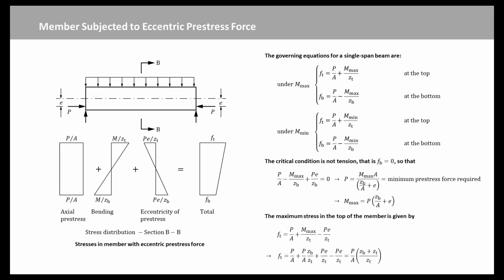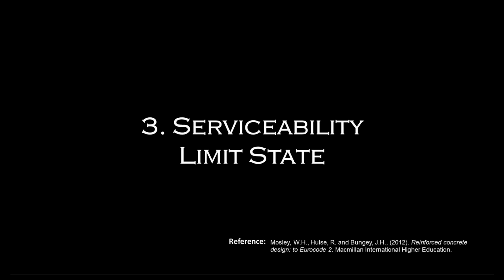The maximum stress in the top of the beam can be derived as these equations. This equation is the same as that obtained in the previous part for an axially pre-stressed member. Thus, the advantages of an eccentric pre-stress force with respect to the maximum moment carrying capacity of a beam are apparent. Next, we will introduce the design for the serviceability limit state.